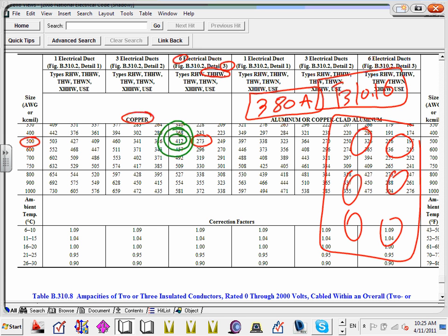It is what it is. When systems are energized, with the air handling units, you have 5 of them, they don't kick in at the same time. It's a very, very small amount of time that you're going to pull closer to 4,000 amp, because of the safety margin that we built in. Anyway, that's my justification for when we have to use 380.